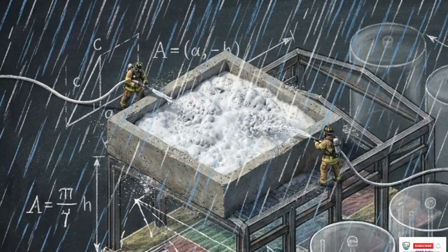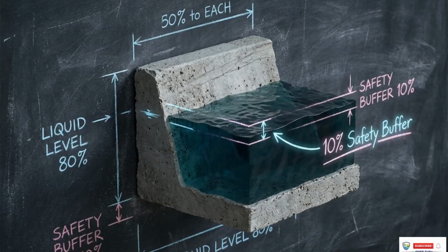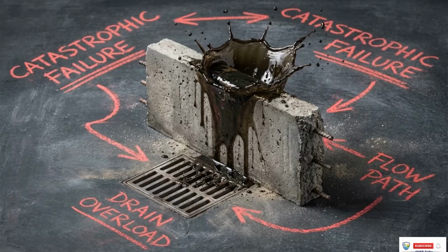This extra capacity is an operational necessity, accommodating heavy precipitation from storms and the massive influx of fire suppression foam during an emergency response. Accurately calculating this final 10% buffer dictates whether a localized spill is safely managed or whether it overtops the wall and escalates into a major federal environmental incident.